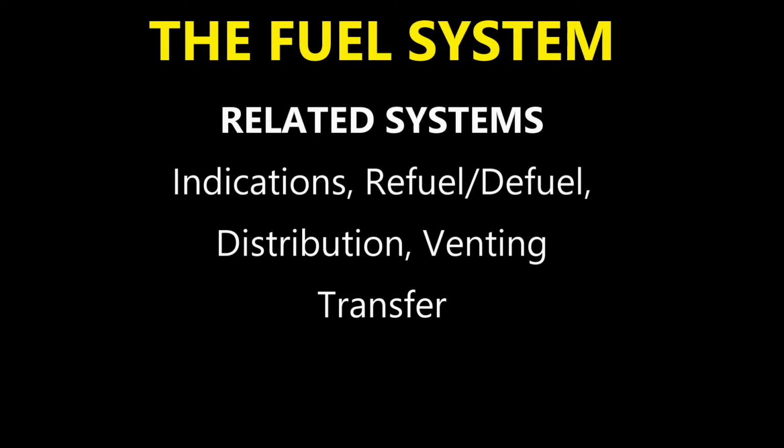During the auto fueling, we're auto fueling with the refuel valve switches in the normal position. The mode select is on refuel. Then those valves are going to open and the tanks are going to start to fill.